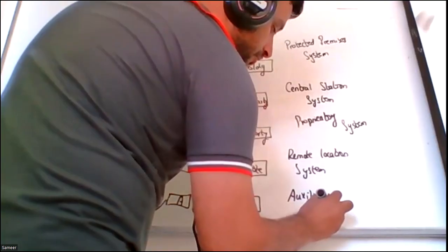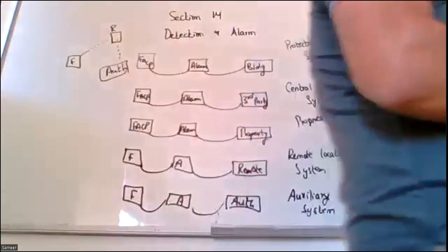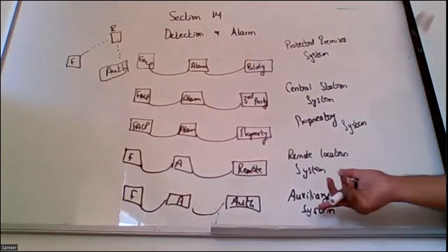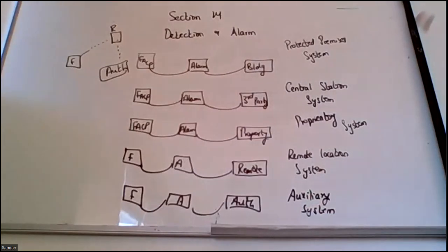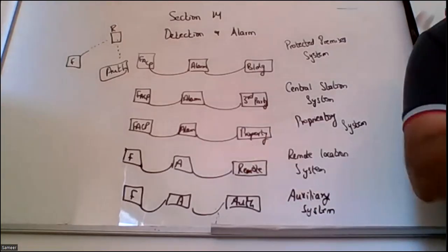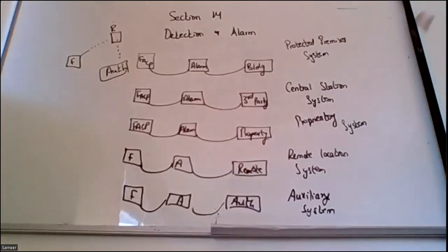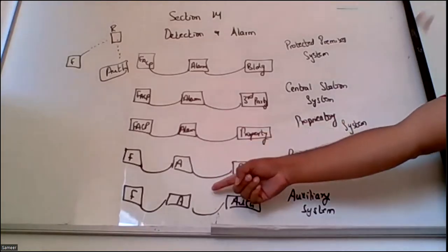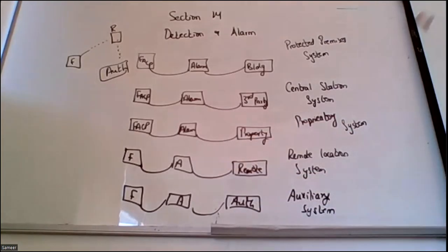Usually you'll see that in most of our facilities now in Dubai, they all have 24/7 boxes. Now in Sharjah also, a new project, Aman, has started, and they have also started with the same 24/7 boxes. Any alarm, any fault, Aman will receive it. So a fire alarm directly sending a signal to the authority is the auxiliary system.